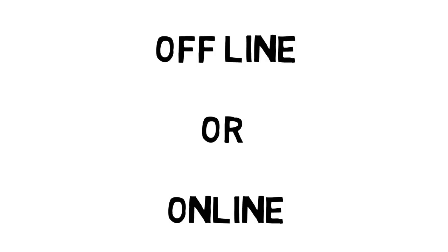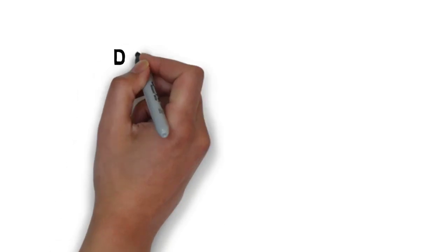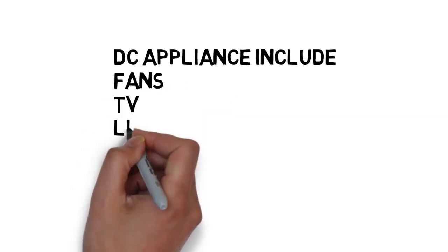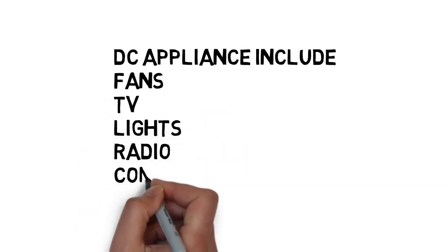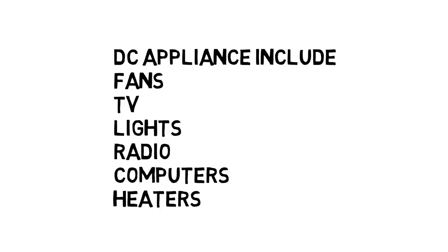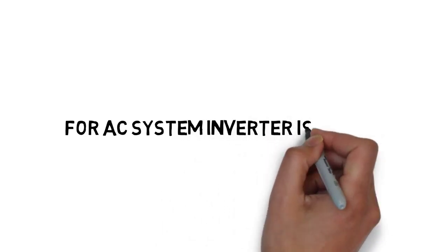Where there is no connection to grid electricity, solar PV systems can be used with both DC output or an AC output. It should be noted that contrary to the popular belief, a lot of appliances are available that run on 12-volt DC current. Most electronic devices in fact are DC based. Televisions can be bought with DC input and so can be fans, refrigeration devices, lighting and even heating devices. In fact, using DC output of the panels in the DC appliances eliminates the need of an inverter.